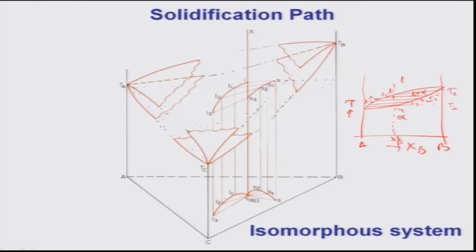As I know their compositions, I can easily explain how the solidification is proceeding. I can calculate volume fractions of phases very easily, which is not possible using the 3-dimensional model. In the 3-dimensional model you cannot use these compositional data points to calculate volume fractions, how the solidification is progressing, or the composition of the solid product. You can do that easily if you project these things.